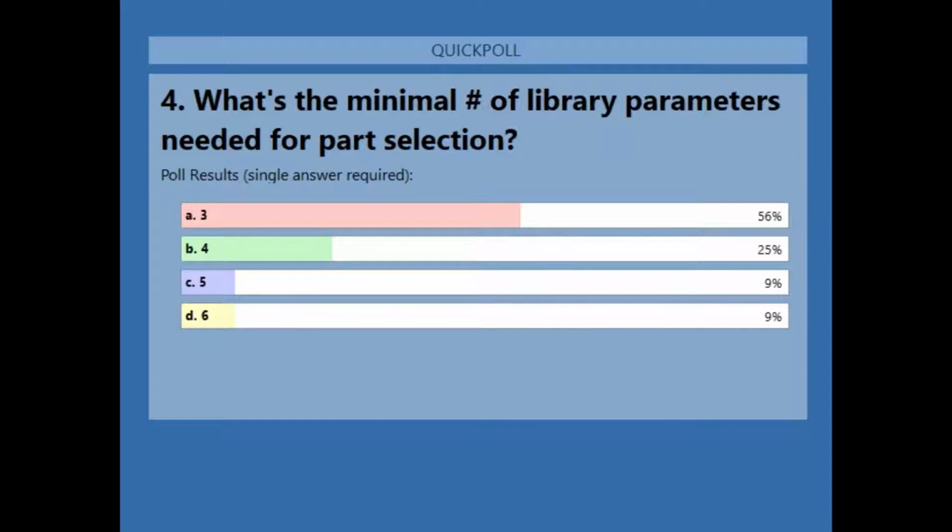The other one we want is status or availability. And this, of all the parameters, to me, is one of the most difficult to maintain, because manufacturer's name and manufacturer's part number, if you think about it, are pretty stable. They're pretty static. Now, granted, manufacturers' names do change over time due to mergers and acquisitions, but even then, let's say Altera recently got bought by Intel. Well, they're still probably going to call it the Altera line for quite a while, right? It just takes a while for those things to change.